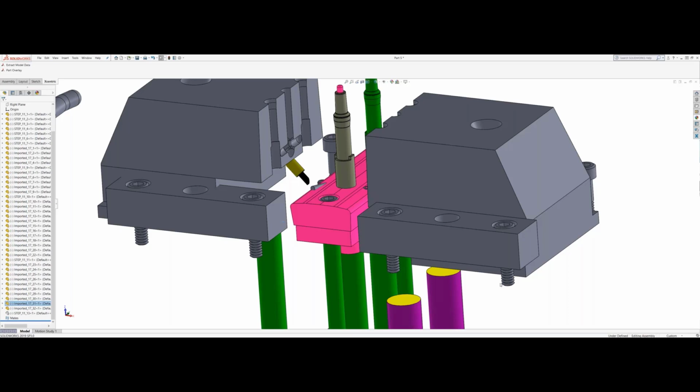In this case, we're not running at a normal production rate of 10, 15 second cycle times. Something like this would probably be 25 to 35 seconds. So we've got ample cooling in between cycles. But yeah, we don't have any specific conformal cooling within the tool, at least these tools. Not to say we can't do it. We've done it with production type tools. But this one was a prototype to do a small scale mimic of the production tool.